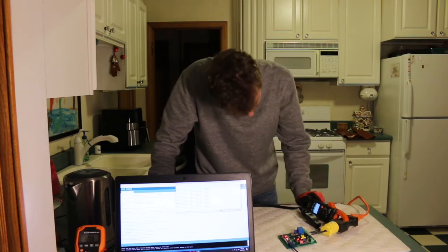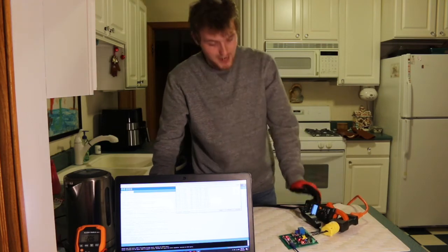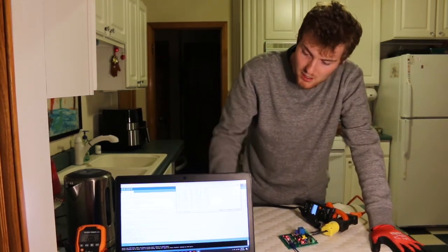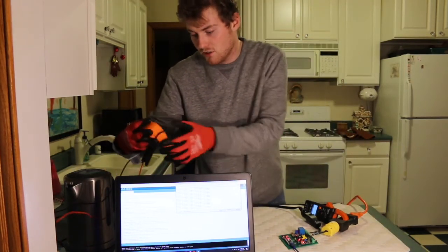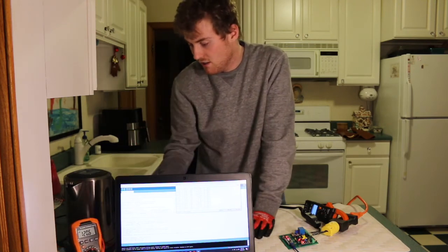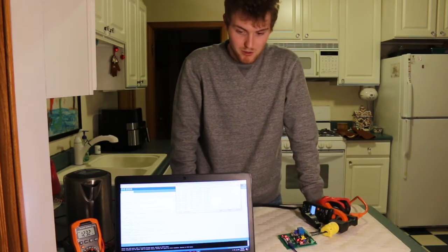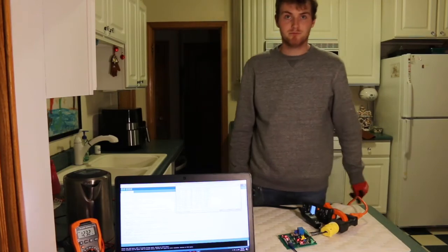So as we turn on, we're seeing 12.13 amps, and we will verify that data with the Arduino serial monitor. As for voltages, we're currently seeing 120.6 volts coming from the mains outlet, and we will check back in with the reported readings from the serial monitor.